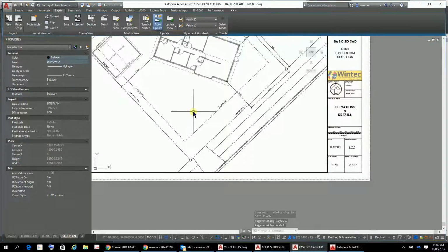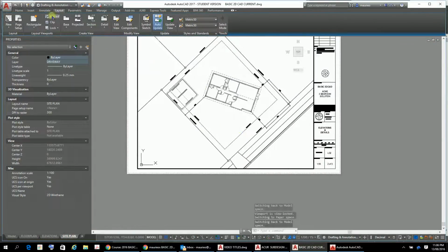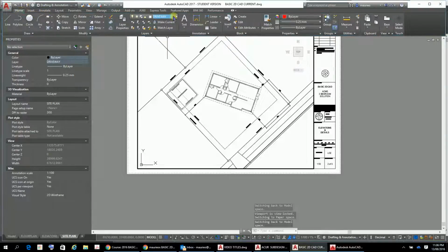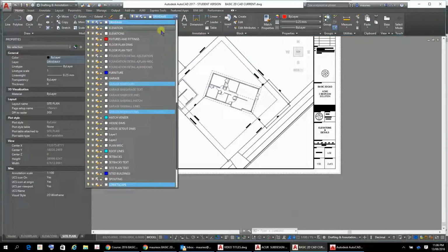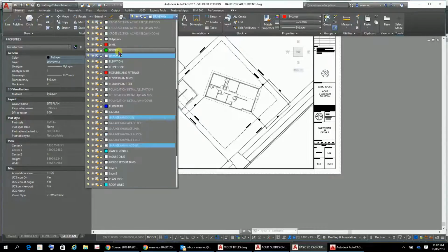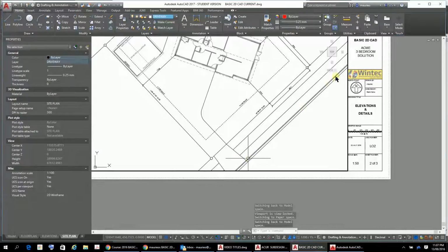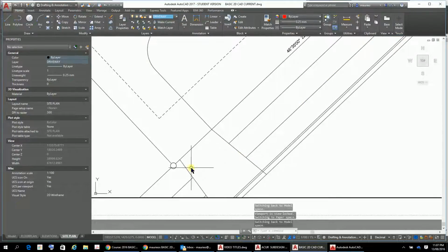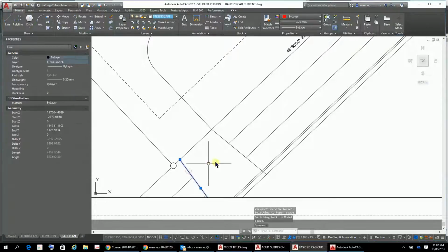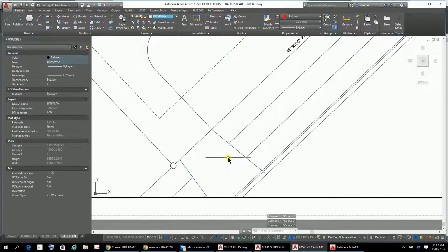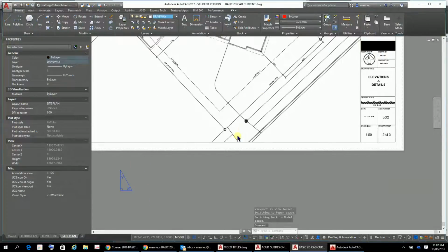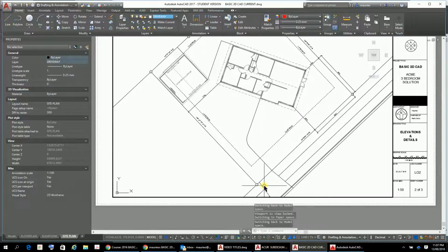So if I go back to my site plan, and you can see that those layers are not turned on in the thing there. There's driveway, so I can turn on the driveway in this viewport going up there, so just turn it on there. Yes, there's my driveway. Oh, there's my driveway in. And there was one other thing I think I wanted to do. I think in my previous examples I just made, no, I'm going to leave it like that for now, and we'll see how we go.